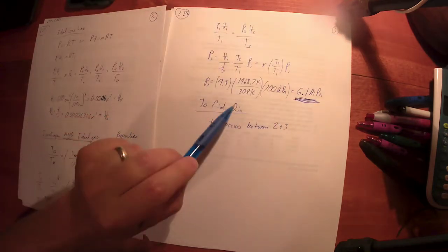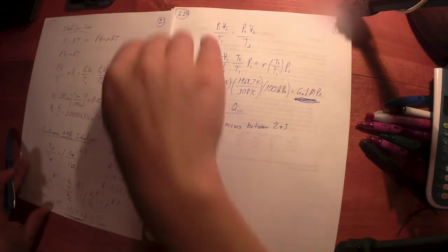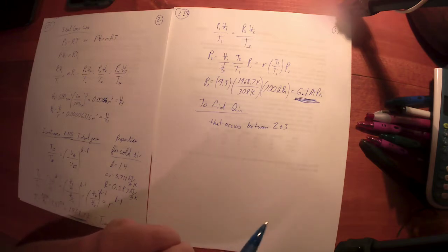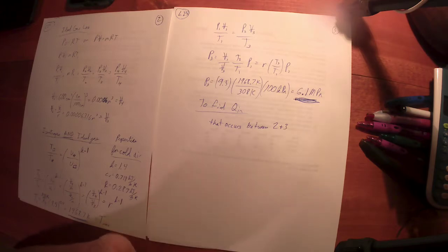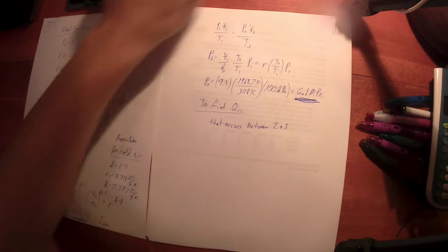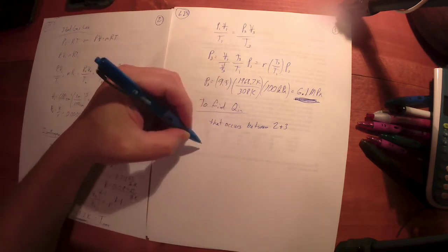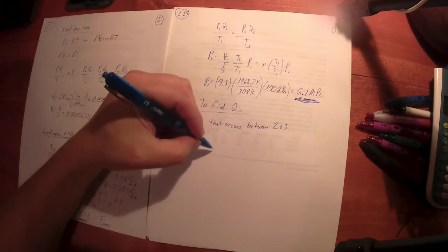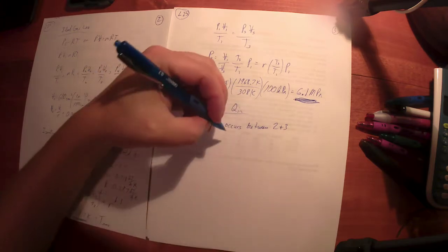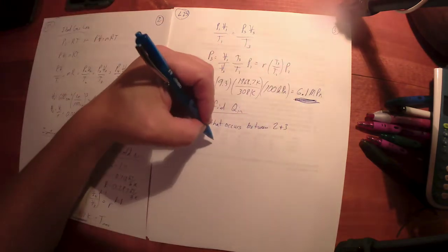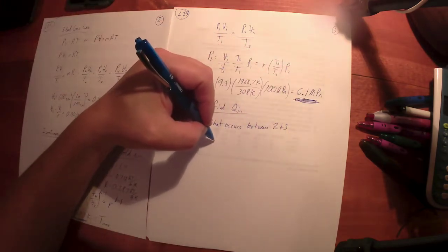Okay. What is a good tool to find heat transfer? Pause if you need to, but guys, at this point in the semester, that's got to be a gag reflex. You should be yelling at your screen right now, first law, right? And make the people around you uncomfortable. First law, yes. Anytime you need to find an unknown energy, the first law is a nice tool. The second law will let you find an unknown heat, but we don't have a constant temperature, so it's a little trickier. But the first law, I think, works just fine.